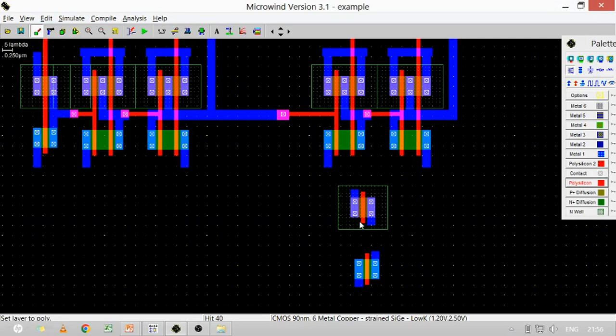So we are connecting the polysilicon with polysilicon. It is not aligned, so try to align it. It's aligned. So connect their drain connections. This for VDD. Try to work zoomed in, else we can mismatch the layer. Fine.